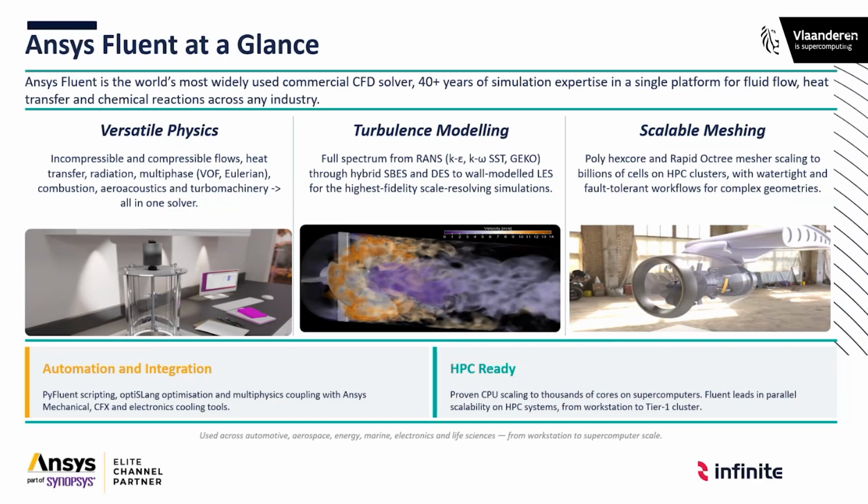It has versatile physics. It can handle any type of flow, from a laminar pipe flow to unsteady LES simulations. It can be used in combustion together with radiation. We have a wide spectrum of turbulence modelling, from RANS up to stress blended eddy simulations to LES simulations to achieve the highest fidelity scale resolving simulations.